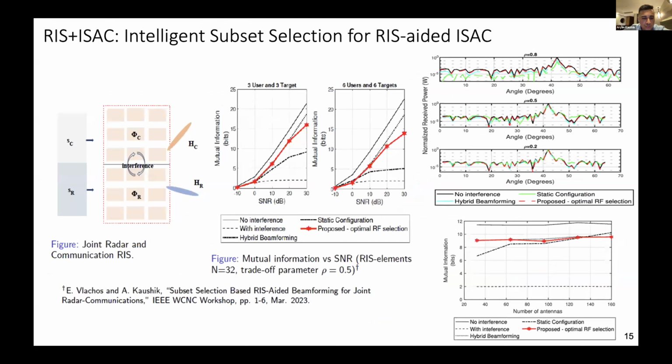You can also combine these technologies with other technologies. Let's say ISAC was one of the important technologies, as I discussed in the beginning of my lecture. So you can also combine these intelligent metasurfaces with ISAC signals as well. So you have a dual-functional signal, right? Instead of sending just a communication signal, you're actually carrying information for both communication and, if you want to, detecting any targets, objects, and so on. So you are able to perform these optimizations that I was talking about together with this dual-functional signal as well. Then you can see the trade-off between sensing and communication. Sometimes one of the performances gets dominant, the other is not that dominant, depending on how much weighting you give to each operation, right?